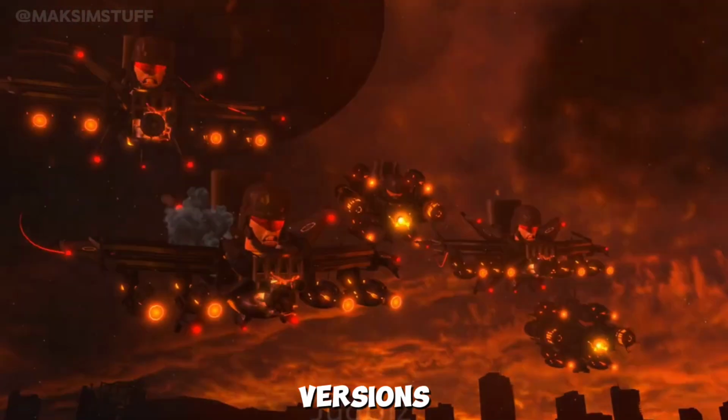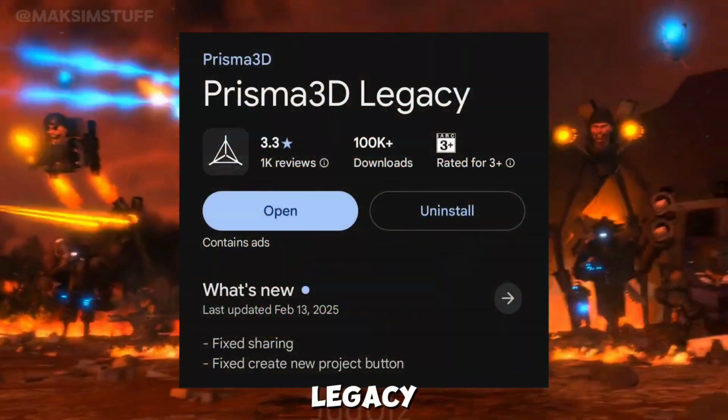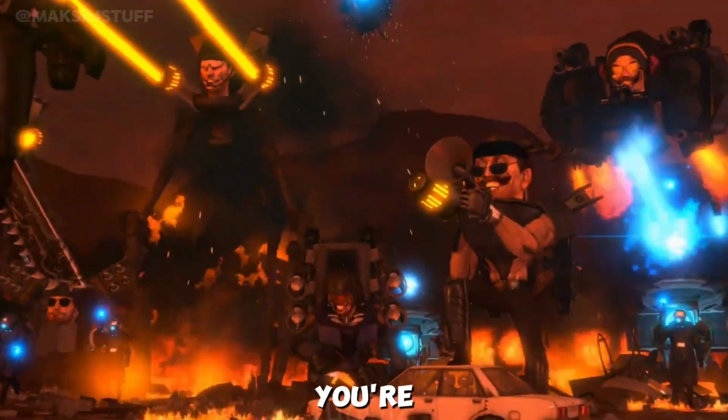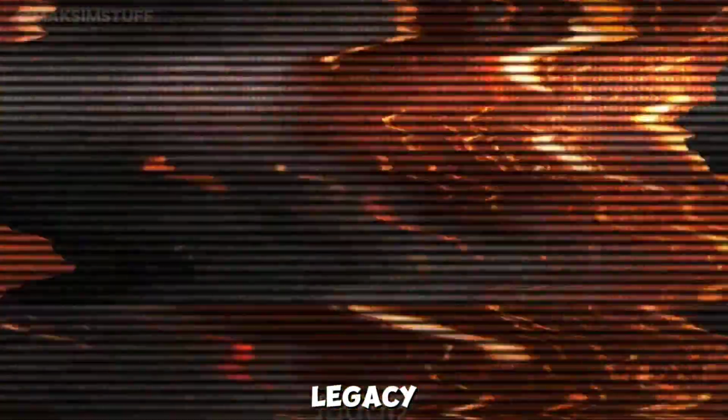The second common mistake is using the wrong version of Prisma 3D. There are two versions: the regular Prisma 3D, and Prisma 3D Legacy. Legacy is an older version, and it does not support these particles, so make sure you're using the correct version, the regular Prisma 3D, not Legacy.